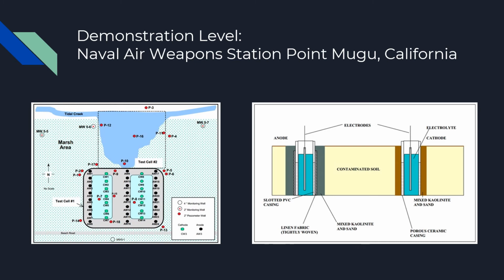These lagoons were online and were in use between 1947 and 1978, when it received wastewater from the electroplating and metal finishing plants. The plating shop discharged about 95 million gallons of plating rinse solution and some organic solvents into the lagoons. In addition to this, the lagoons were also the dump site for 60,000 gallons of waste photographic fixer